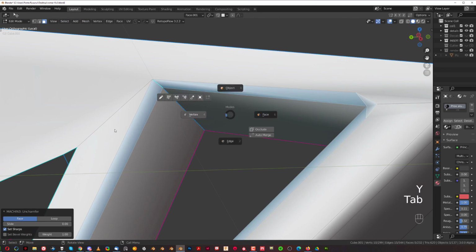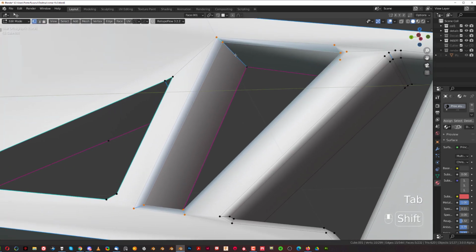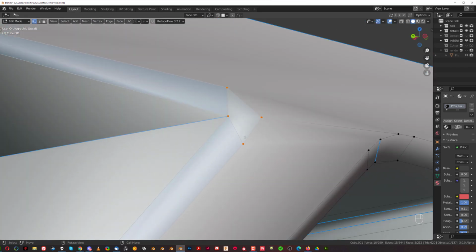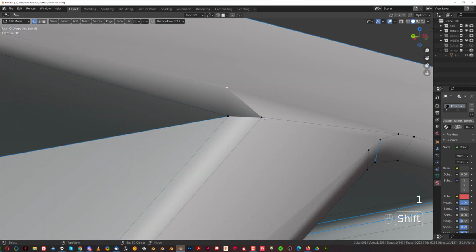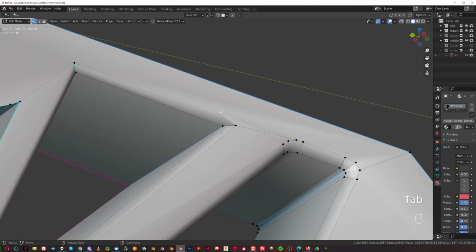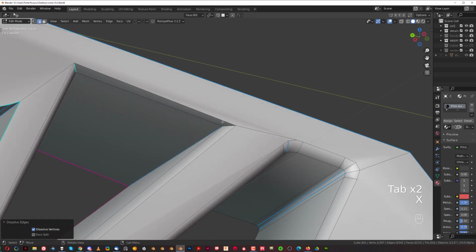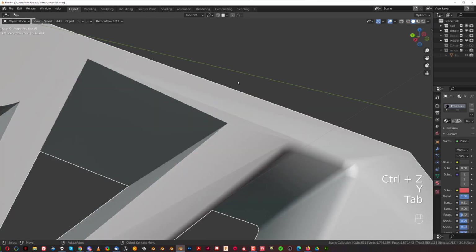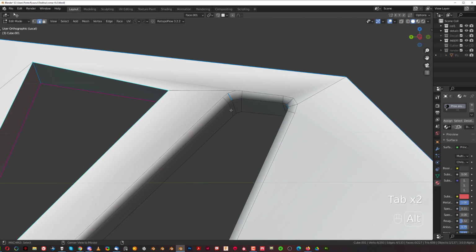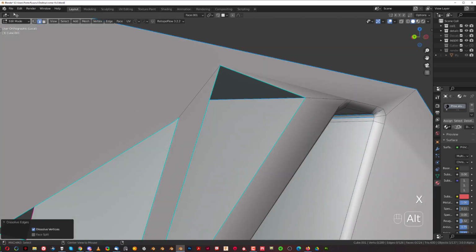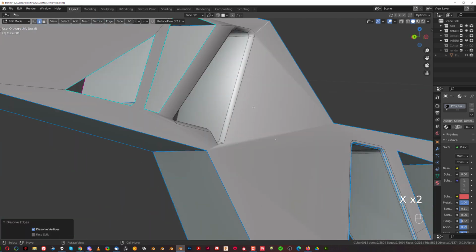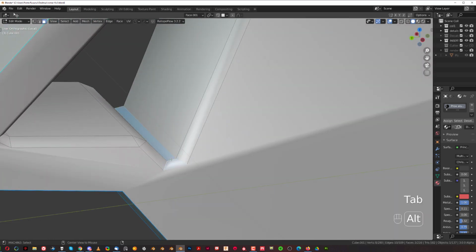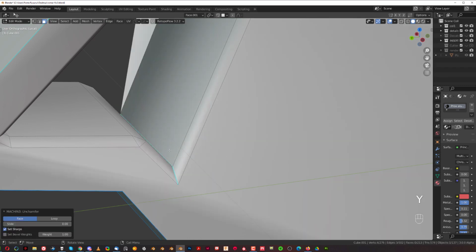Whoa, that didn't work. Okay, fair enough. Let's combine them here. If it will even work. We could dissolve this and then unchamfer here. Perfect. And then we have one more, right? So unchamfer these and we're done. So let's select this one here and unchamfer.